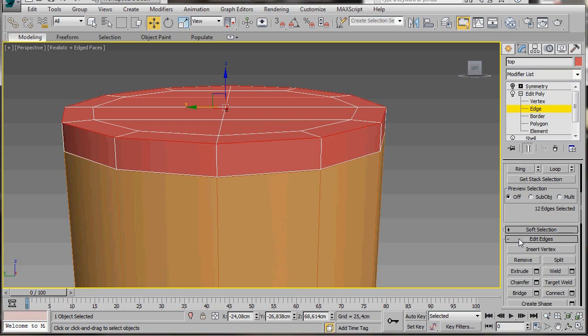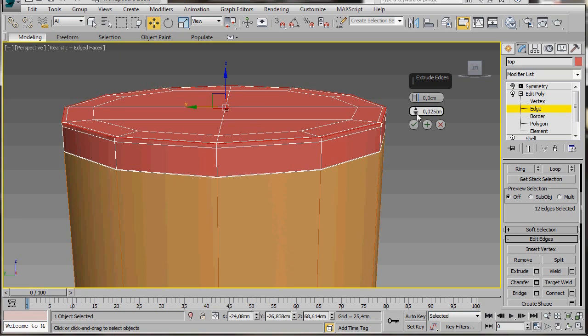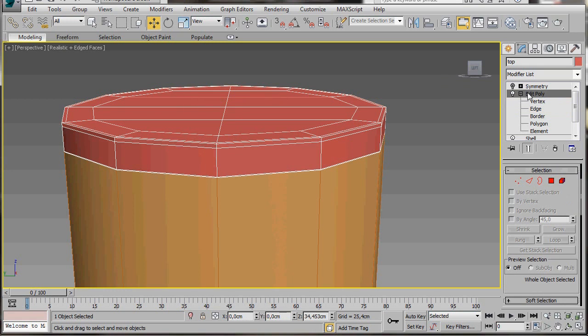Now let's pop back over to the panel and we're going to scroll down and click on the Small Settings icon for Extrude. Let's have a wee look in the caddy. I'm going to right click on the bottom dials and bring both of them back to 0. Then I'll come over to the spinner for width and just click it once. That will bring me to 0.025, and then I'll press OK. I've just created 2 extra loops, one on the top and one around the side.